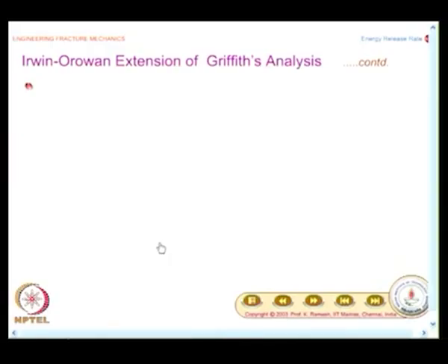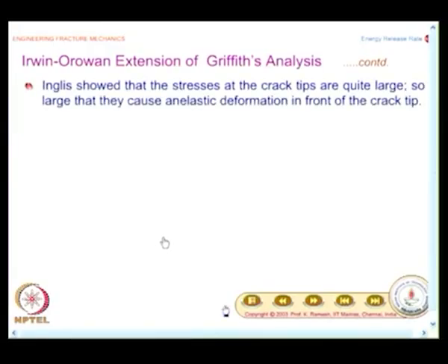And what is that physical phenomenon in the case of ductile materials? It is the plastic deformation, and the moment you come to plastic deformation, what happens? It is irreversible, energy is lost. It is not like a reversible system. Whole of Griffith theory, he developed this energy balance based on the premise that the system is reversible. So, now we have to make a very important engineering step for us to apply fracture mechanics to ductile solids. It was done by a very simple modification,